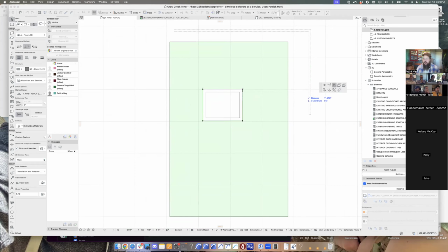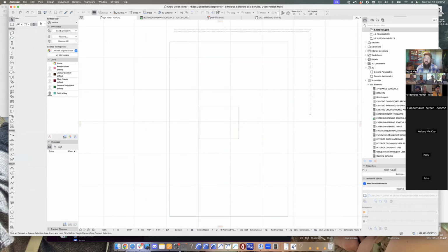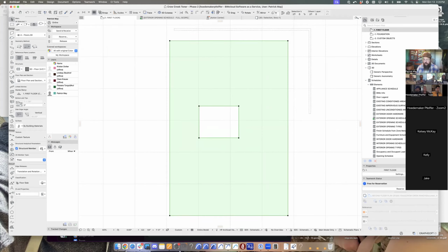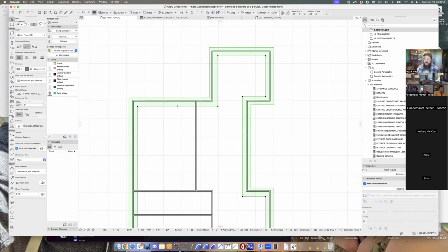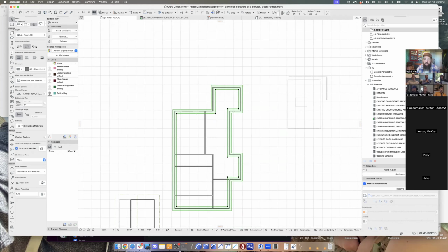So I can adjust the boundary of that. I can add a node to that, stretch it. I can move it using the drag command. If I reselect the whole thing, it's going to move the whole thing. But if I just click on that inner boundary, I can then adjust that. And that can be useful because maybe there's a strip footing that needs to come across this way. So if I grab that edge right there, I can hit plus and add the strip footing here and get really sculptural that way.